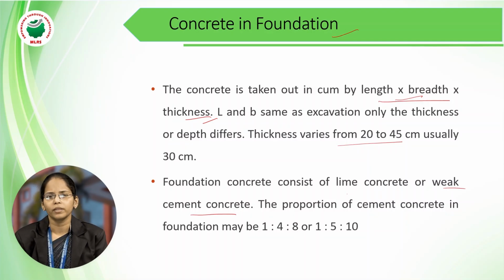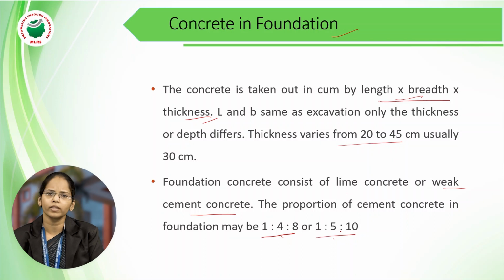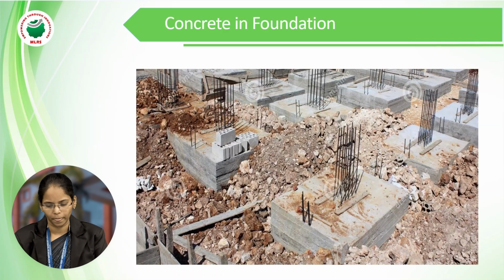So PCC is laid first on the ground, below the ground level, in the substructure. After that comes the mat or raft foundation. Any foundation based on that will provide a mat, RCC mat. So we need to define that proportion. Either it may be 1:4:8 or 1:5:8. We need to define it, and we need to prepare an estimate. Next, see, this is the foundation. These are the steel bars which we use. This is the concrete in foundation. These all are the foundations.